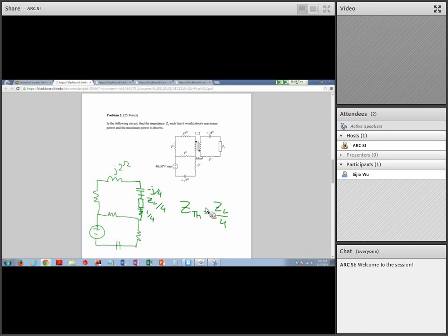So when the ZL is the open circuit, so it's just the bottom one? Just the bottom loop. Because the top one will be the open circuit. Yeah, right. Top one would be 0, so you have to find the voltage across this resistor, because there's no voltage drop across any of the elements. So the voltage drop that's here is going to be the voltage drop over the open circuit.